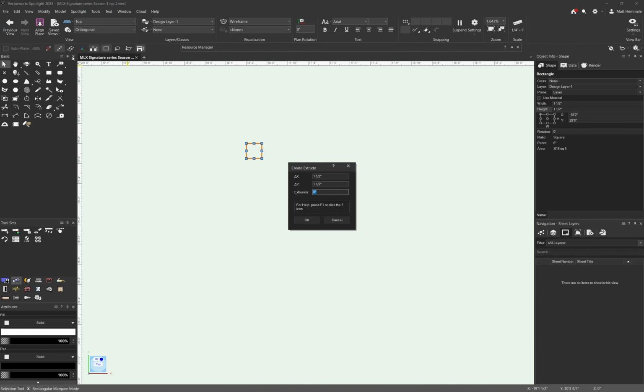And 1.5 inch pipe comes in standard. You can get them from like Ferguson Plumbing, but just about any place. It's a standard 21 foot. So 21 foot pipe is threaded on both ends. So if you buy it, it's 21 feet and you got to cut it. Which means it leaves you with one end or two ends, depending on what you need to cut, with either one thread or no threads. So something to be aware of.